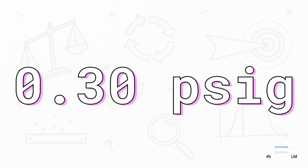Now for the fun part. We take those individual numbers and we plug them into our root sum of squares formula. We square each one, we add them all up, and then we take the square root of the total. The result is our combined standard uncertainty, our UC. And for this system, it comes out to 0.30 psig. That's pounds per square inch gauge.